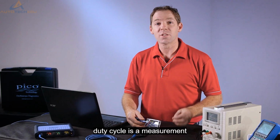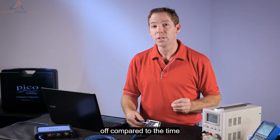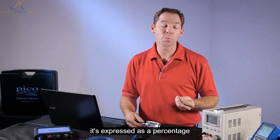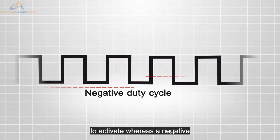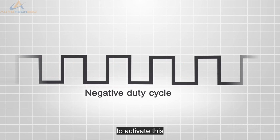Duty cycle is a measurement of the amount of time the control is on or off, compared to the time of 1 complete cycle. It's expressed as a percentage. A positive duty cycle is held to ground and pulled high to activate, whereas a negative duty cycle is held high and pulled to ground to activate.